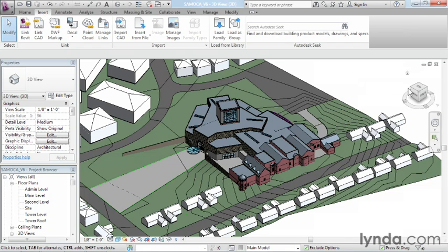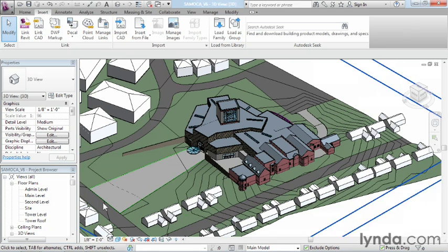If we wanted to add a decal to the turret here on the townhouse, that would work just fine. But if it's curving in two directions at the same time, then the decal feature doesn't work. But it turns out that we can create a custom material instead and achieve basically the same result. It just takes a little bit more effort to set it up. So let me show you the process here.